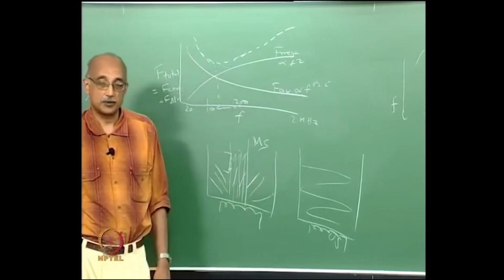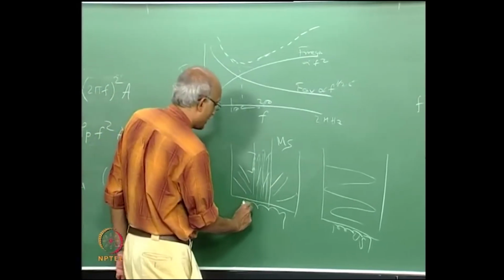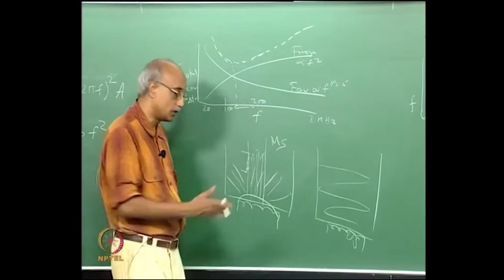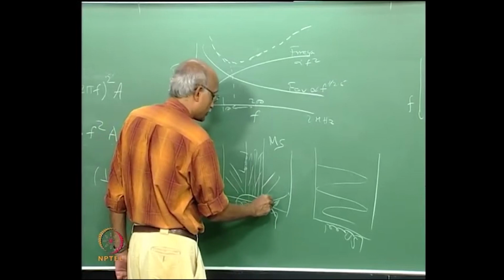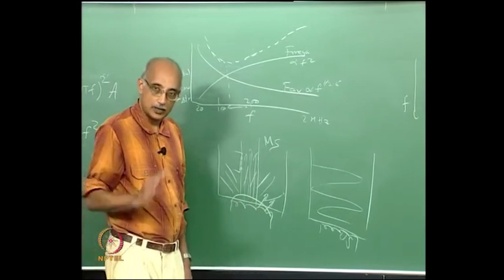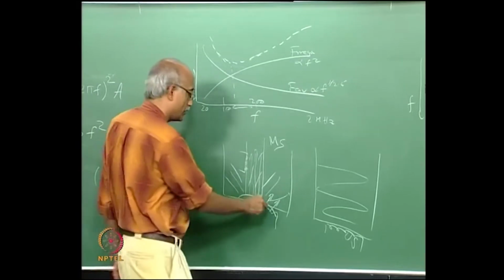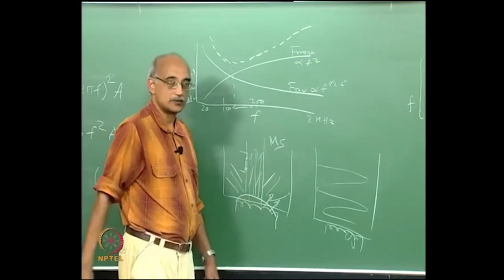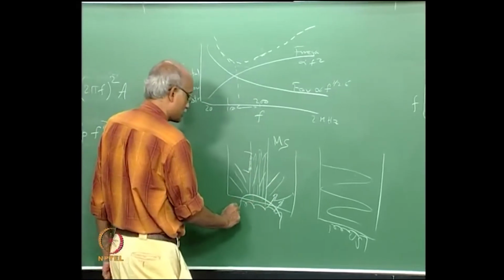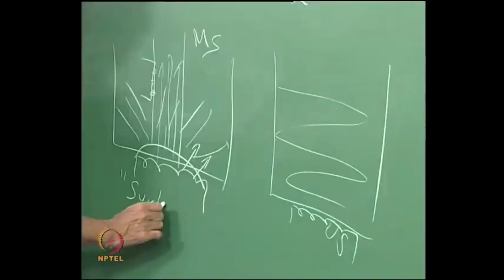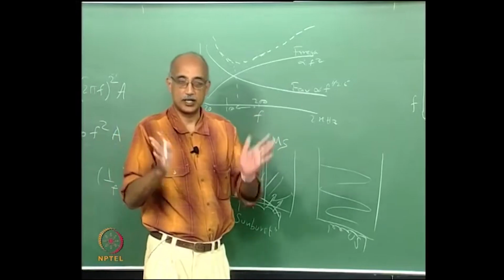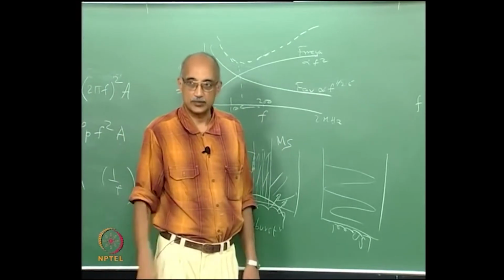The other way that people have tried to do this in the past is having a hemispherical transducer, which essentially has the same effect because the field is normal to the surface. So, if you have a hemispherical transducer and you have the force propagating normally at every location, you should get good coverage of the entire surface. This type of megasonic cleaning is called sunburst megasonic cleaning because this design makes it look like rays of the sun propagating out of this hemisphere.